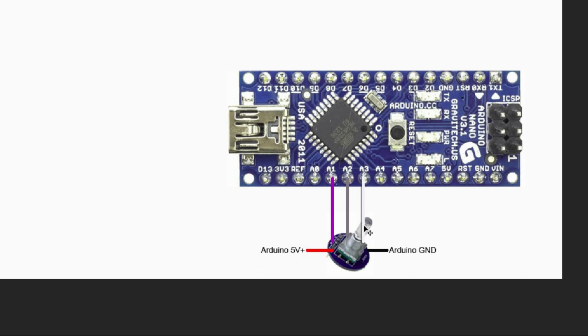Why do you need 2? So that you can detect clockwise or anti-clockwise situation over here. You can probably find other rotary encoders in this sort of setup, so you can use them as well, if it's not the exact one that you see here. If you want to get a rotary encoder, get something that already has the capacitor and resistor soldered on it, so that you don't need to do that to clean up the signal.